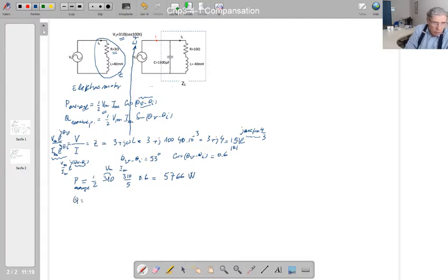If you do the calculation for the reactive power, these are going to be the same, but this is going to be sin 53 degrees. If you do this calculation, you're going to end up with 7,665 VAR. So what happened here? Interpretation of this analysis tells us that is the useful power. But we are taking that amount of current from the circuit. This current determines this reactive power. So energy supplier companies say that they are going to charge you for this power as well. Not the useful power only, but the reactive power as well.